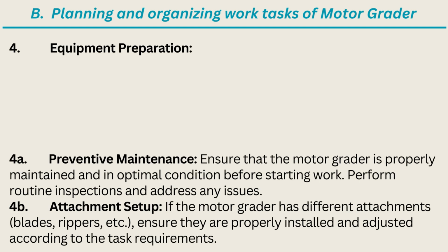4. Equipment preparation. 4A. Preventive maintenance. Ensure that the motor grader is properly maintained and in optimal condition before starting work. Perform routine inspections and address any issues. 4B. Attachment setup. If the motor grader has different attachments, blades, rippers, etc., ensure they are properly installed and adjusted according to the task requirements.